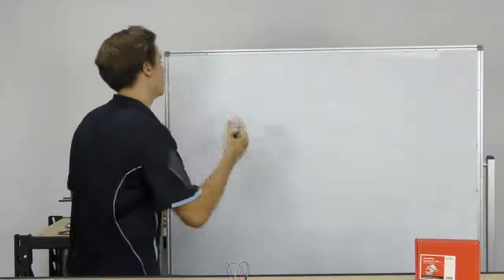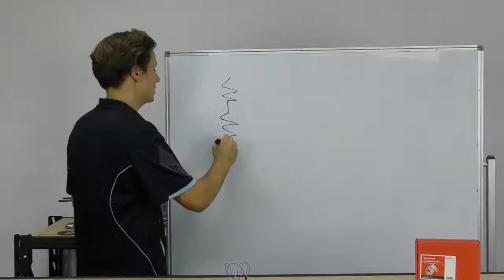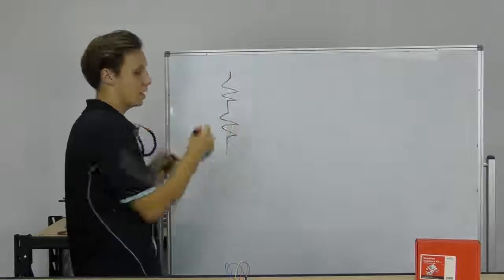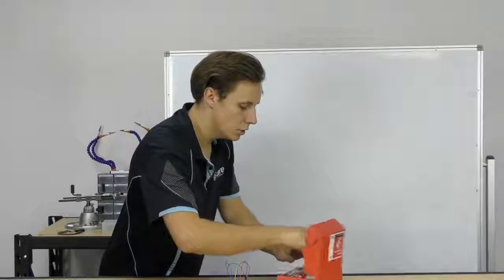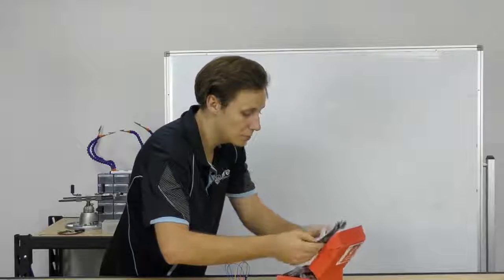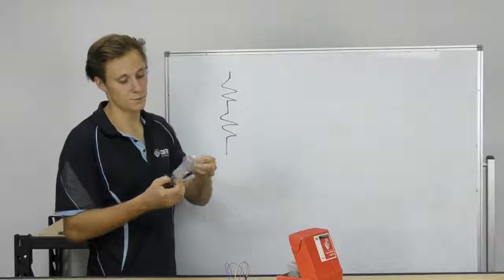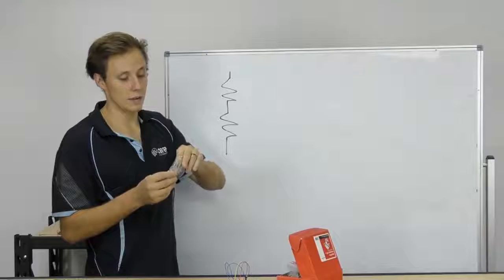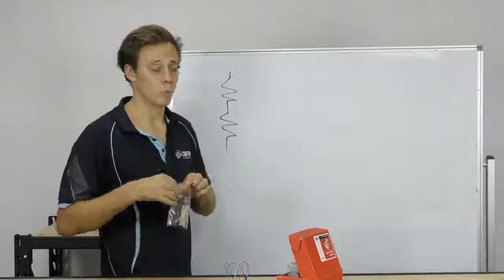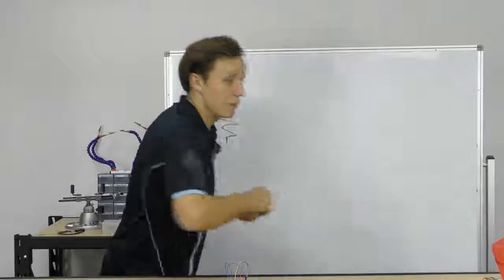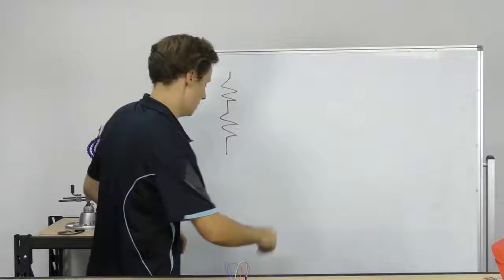Well, a potentiometer, the way it works, can be thought of as two resistors connected like that, and a potentiometer has three legs. There's one in the SparkFun Inventors kit actually. It's a smaller one, known more properly as a trim pot because it's small, designed to be on a board and used for controlling or adjusting different values, either for a digital system or an analog system. You can get larger ones which you can use for real-time control on panels and things like that. But they work exactly the same way. Here's one, very little, three legs.